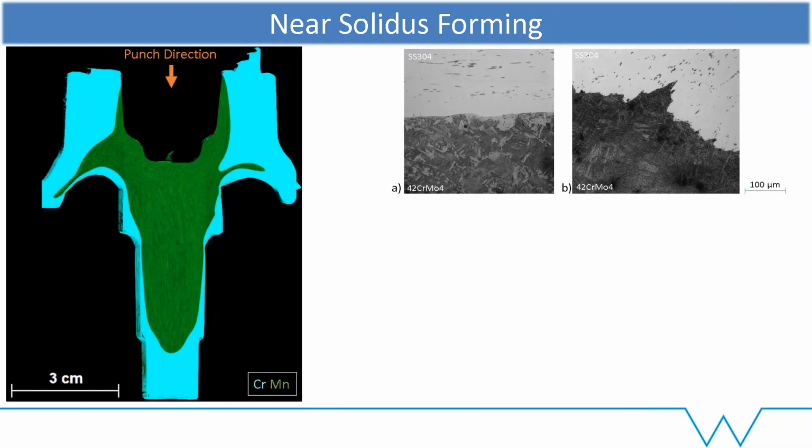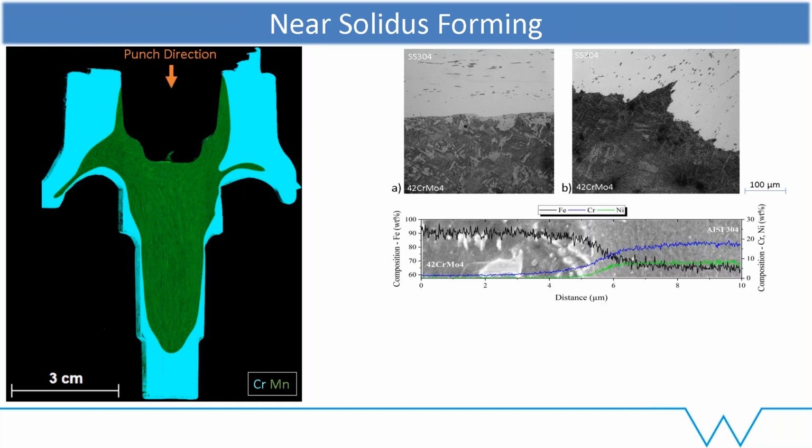If we look into the microstructure of this, then depending on the different locations, we've either got a very flat surface or a rather serrated surface. We need to do a bit more work just to see which is better in terms of mechanical properties. Is it better to have the larger contact area of the serrated one, or does that add to stress concentrations? But what we don't see is porosity, and we don't see intermetallics.